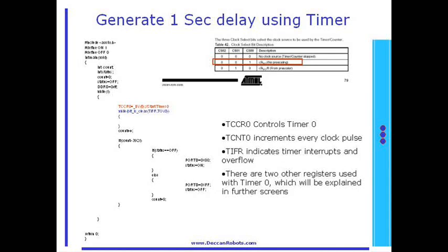If you observe the code carefully, you will notice that the processor is engaged in monitoring the timer overflow flag and its multiplying factor. We can simplify this application using interrupts in combination with timer 0. This will leave the processor free to do some other important task. Also note that this code will not generate a perfect 1 second delay.